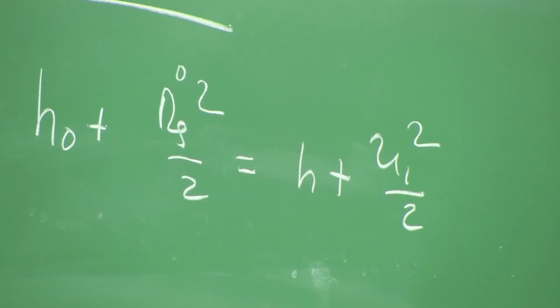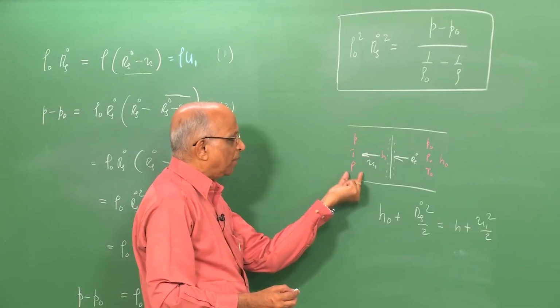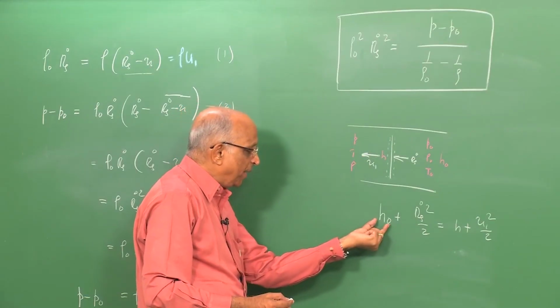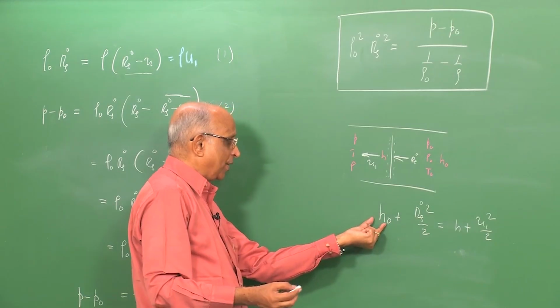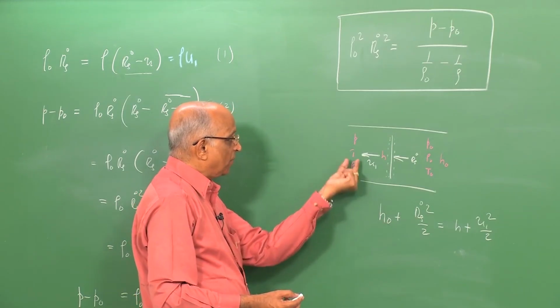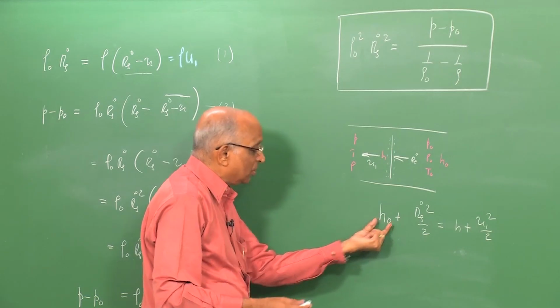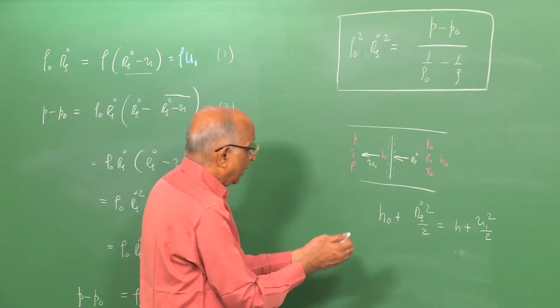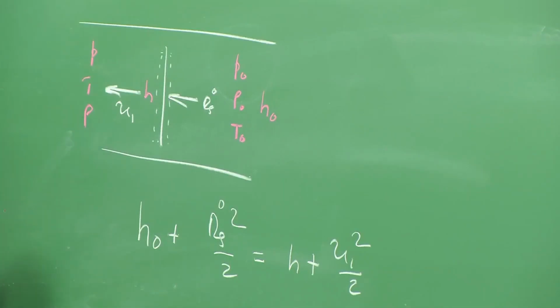Now, if I want to solve this, I have to express enthalpy in terms of these particular properties. Depending on the substance, the enthalpy could be a function. If it is a non-ideal gas, h could be a function of temperature and pressure. If it is a solid or liquid, it is a more complicated function of pressure, temperature and density.